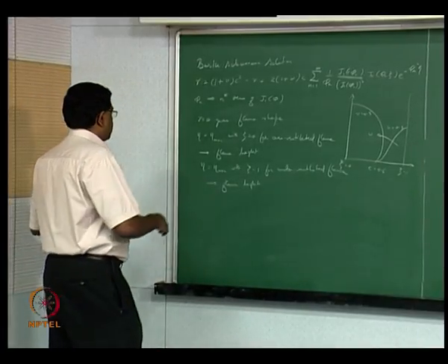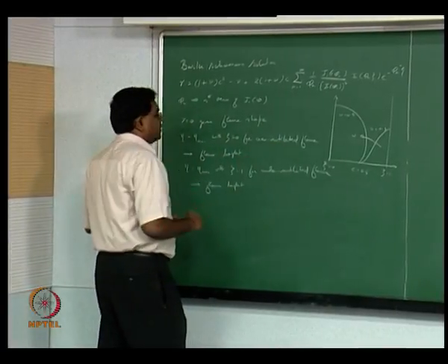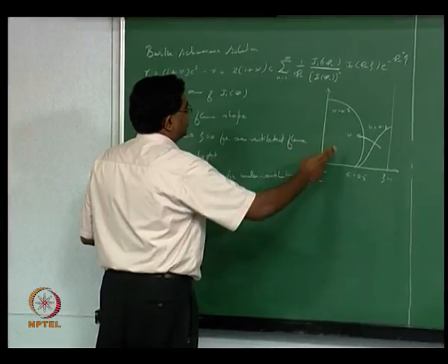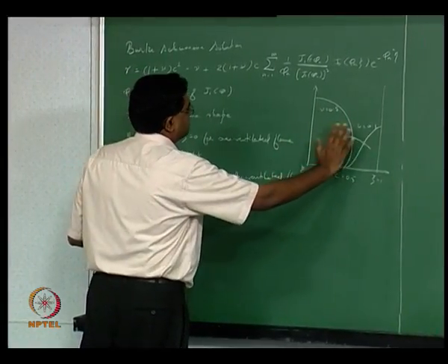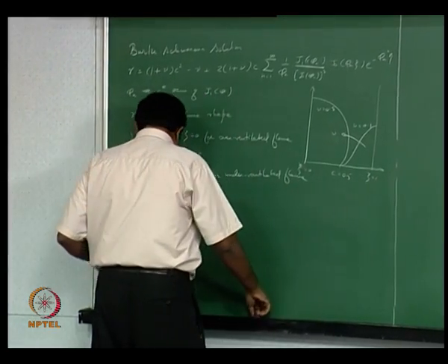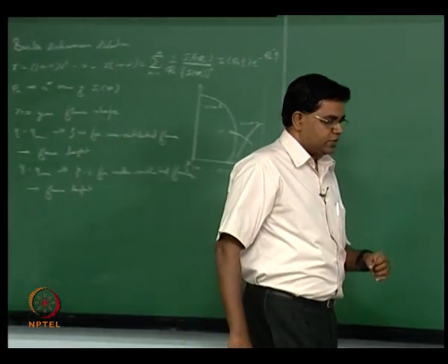you think about it. So the way you actually can find out the flame height is, as I said, gamma equal to 0 is going to give you the flame shape, and of course it's going to switch from an underventilated flame on the one side to an overventilated flame on the other side.